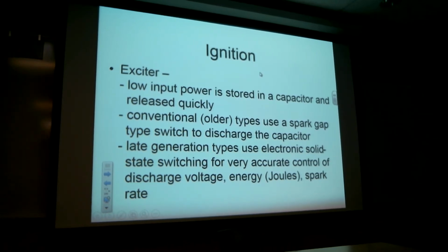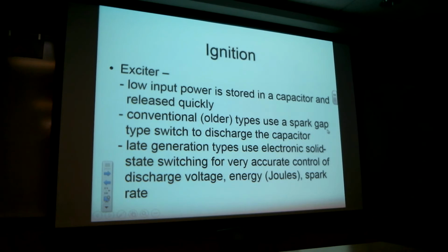So you're saying for a hot day or a hot start, you would need a hotter plug? Yes. Or a hotter spark? And then a cold start, cold day, same thing? Same thing, yeah. And then you wouldn't need so much at other times when the weather's cooler, or maybe it's a secondary start, but you've got good weather conditions. Okay. Anytime the engine tries to overfuel or is susceptible to overfueling, you're going to want a really hot spark. Did you get that? Yeah.